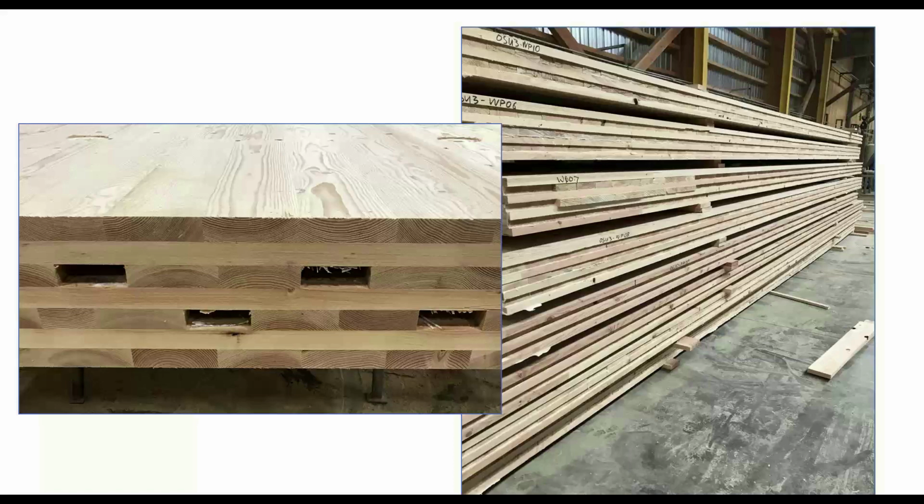The point of that trim is so that we can actually have, within the press area, room to press sideways on the panel in order to have nice tight edge joints, which you see on the left picture. All of those boards are nice and tight to each other. In the picture on the left, we have openings, and those are for post-tension anchor rods for a shear wall. This is for the shear wall that we saw the shop drawing of earlier.